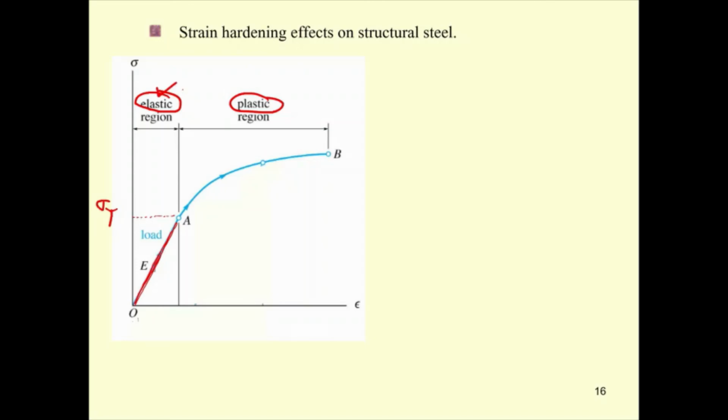But for example, if you have 1 meter of steel and you pull it past this elastic region into the plastic region, say you pull it a small amount, you get 1.02 meters, that's in the elastic behavior, right? But if you pull it to 1.10 meters, it's going to enter the plastic region.